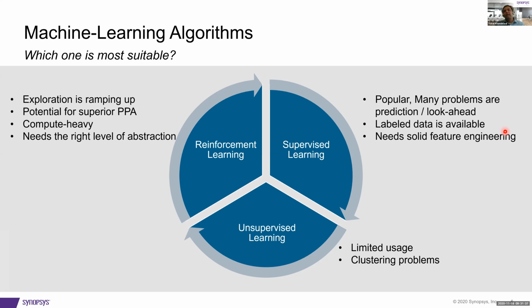We've done some early work in RL. This year we took something as simple as a gate sizing problem, and we've tried to use RL to prove how much is the gap. And we do see that RL sizing can really beat the state-of-the-art sizing engines. And state-of-the-art here literally means, I can tell you, I own the optimization team. We are very proud of our algorithms. We really feel they perform well. So when we beat it, it's a big deal for us.